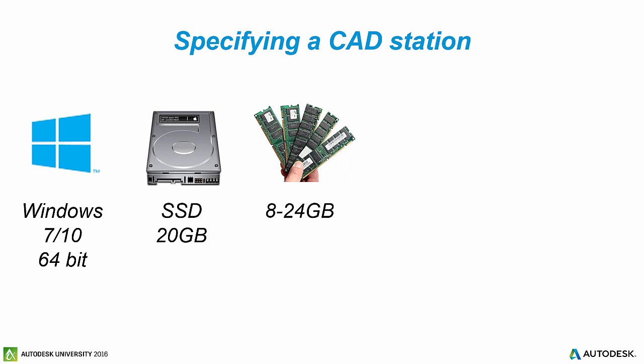That swapping in and out is called your page file. You can tweak your machine to make a bigger page file, and if you separate your partition off your hard drive, you can put one of your partitions as being your page file, and that will write a lot quicker, particularly if your page file is on an SSD drive. But realistically, if we've got enough RAM to support all our model, then that's not an issue. So as much RAM as you can get. Don't think I'll have 8 gigabytes of RAM, I can put more RAM in later. Just try and get it all in there as soon as you can. It makes a huge difference. It's going to make you much more productive.